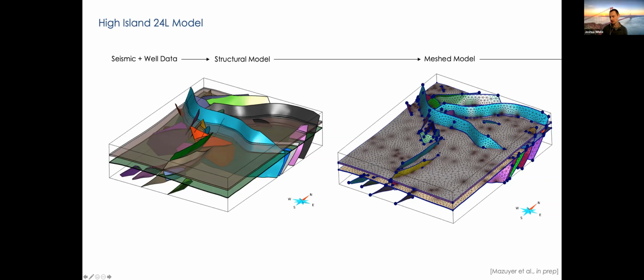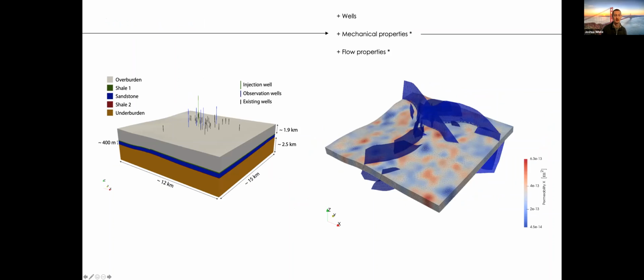In traditional reservoir simulation, when they're just interested in fluid flow, frequently they will build grids that don't necessarily perfectly honor the geometry of these faults. They'll kind of stair step around the faults. But when we do mechanics, because we're interested in understanding the tractions and the stresses on these faults, we're really obligated to have a good conforming grid to these faults. And so that can dramatically complicate the meshing challenge.